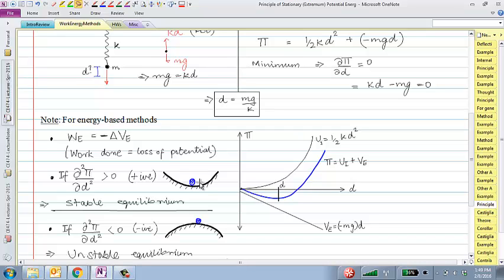Even a slight imperfection, and that column is going to buckle out of plumb. Okay, and that's really a stability problem. So for small forces, the column remains stable, and then if I increase the forces, if we load up our buildings enough, the columns would go unstable. Okay.